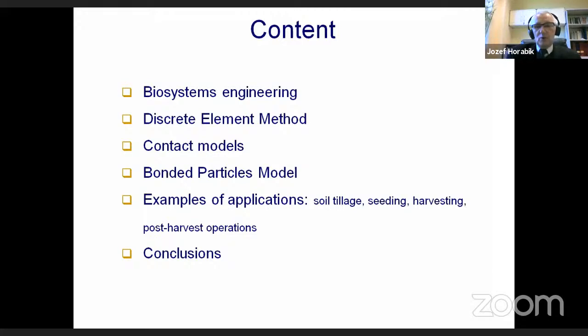Very important point of the discrete element method is the calibration of the parameters. And some of the basic parameters can be determined experimentally in physical experiments, like modulus of elasticity, friction, restitution coefficient. I mean, experiments with a single particle, if the particle is enough big, or in the experiments with the bulk of particles. But in the more advanced problems, some combined calibration method should be applied.